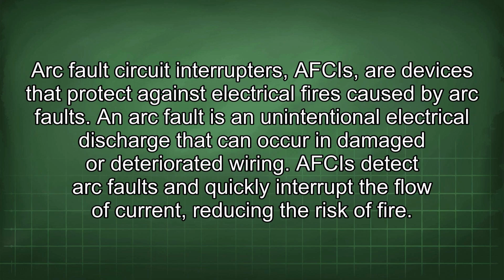Arc fault circuit interrupters (AFCIs) are devices that protect against electrical fires caused by arc faults. An arc fault is an unintentional electrical discharge that can occur in damaged or deteriorated wiring. AFCIs detect arc faults and quickly interrupt the flow of current, reducing the risk of fire.